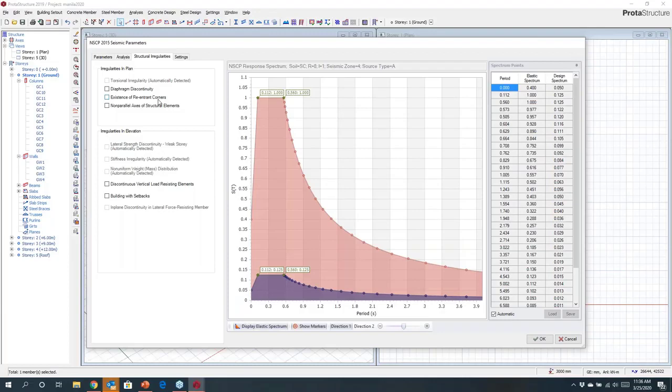If you have excessive torsion within your building in plan, the code will normally penalise you, and you would need to then iterate the analysis. Well, what we will do with these checks is we will calculate what that penalty is, and then we will apply it, and we will automatically iterate the analysis to apply that. So while we're also identifying if there is torsional regularity, we're also calculating the associated penalties and applying those to the model.